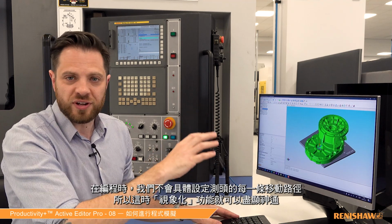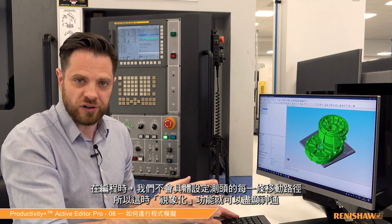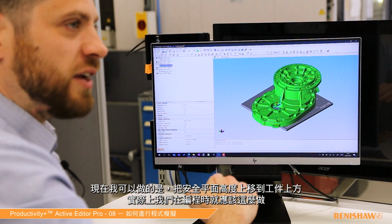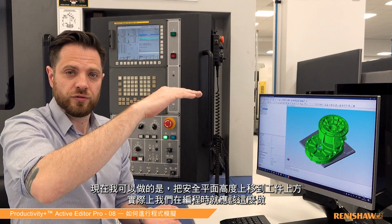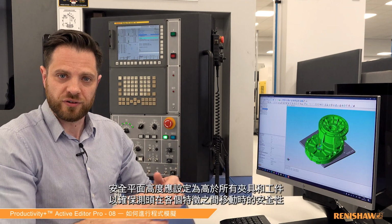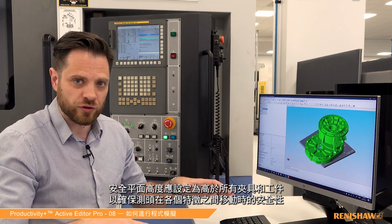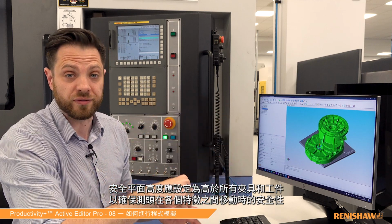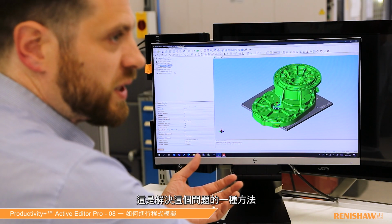So we're not representing every single toolpath. That's where the visualization really comes in handy. Now what I could do is I could extend that safe height to above the job, and actually really that's how we should be programming this. We can set our safety plane height to above any fixturing and the job to make sure that any moves between features are safe. So that's one way we could fix this problem.